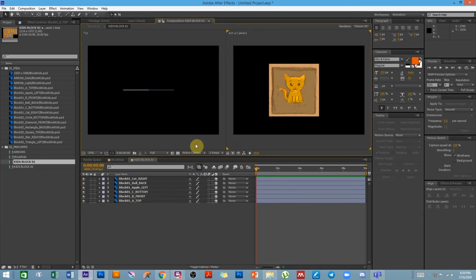Now I'm going to change one of these views to a custom view, which makes it a lot easier to imagine in 3D. How do I know if one of these composition windows is selected? I need to click on it and you'll notice these little yellow triangles at the edge of the tab. That means this window is selected and you can change the view to custom view 1. So now you can see that's 3D, right?